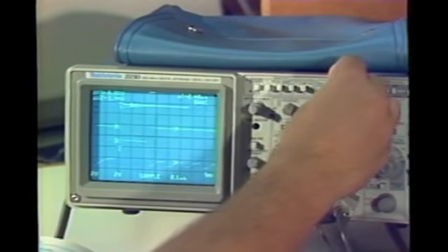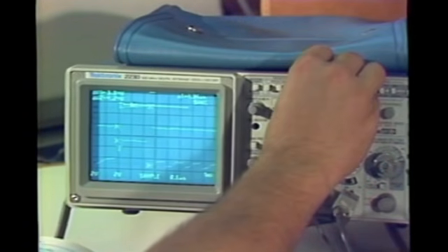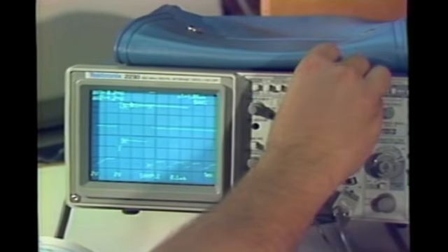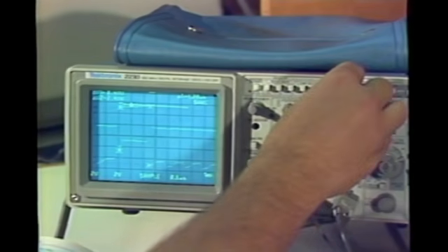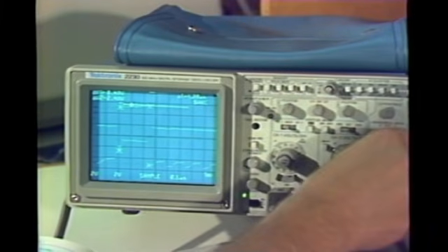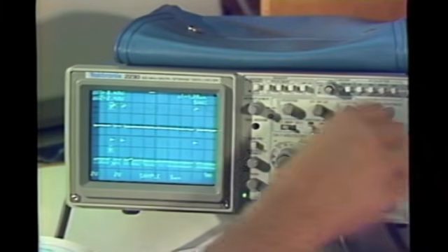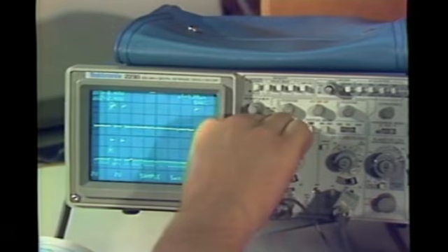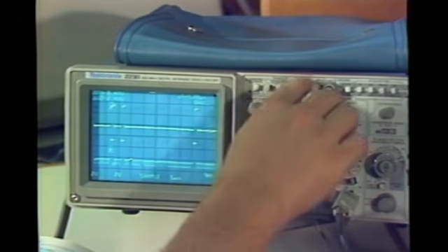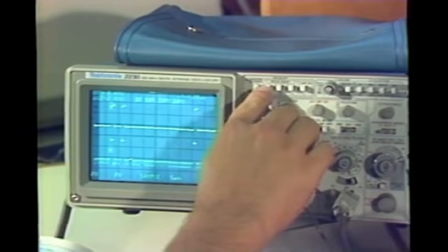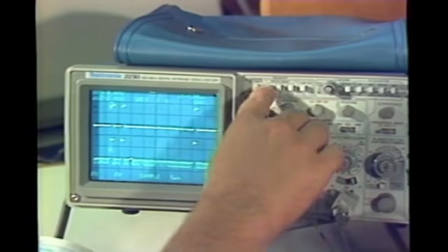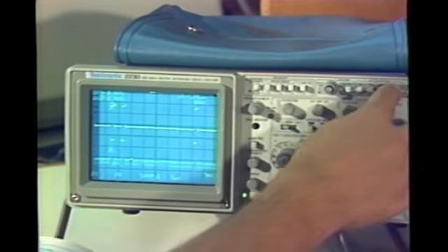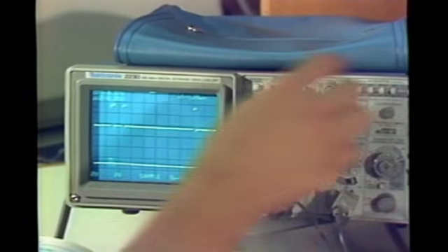For example, the Tektronix 2230 has a 4096-point save reference memory that can store a full 4K record, or alternatively, 3 1K records in 3 individual save reference memories. Any individual memory can be displayed by itself or simultaneously with any or all other waveform memories. The stored waveforms can also be repositioned and expanded or compressed vertically or horizontally.